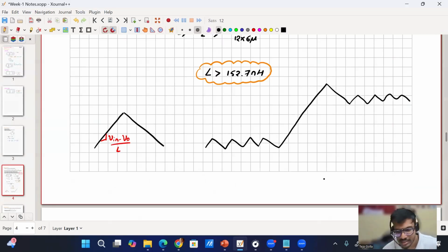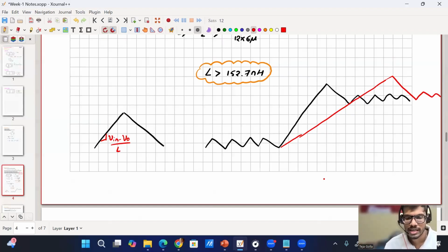then I can go, say this is an optimal condition. Say I'm going from one load condition to another load condition. Now if my slope is lesser, then I'll take more time to reach the same load condition. So my transient response is taking more time. So I don't want to go to a much higher value than required, because that will increase the weight as well as the volume of my converter, and it will degrade the transient response.